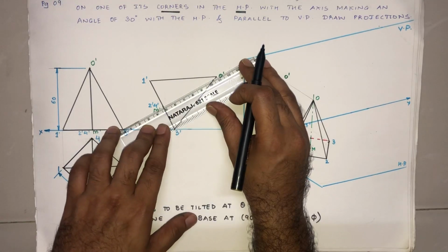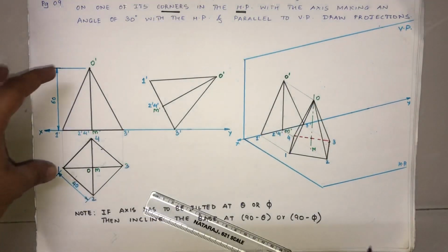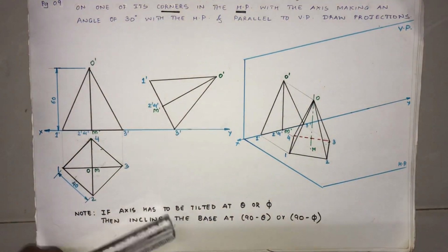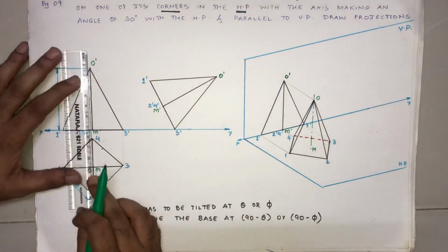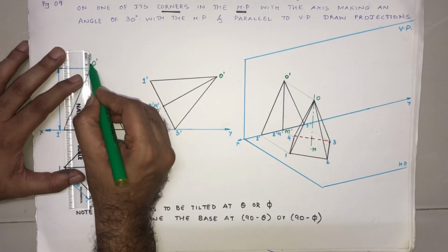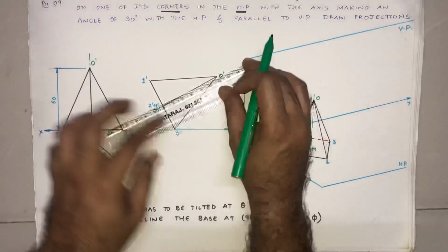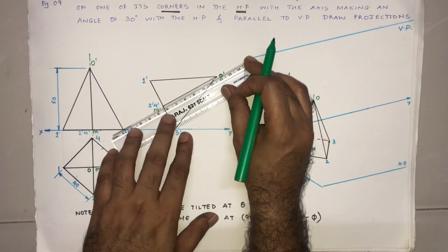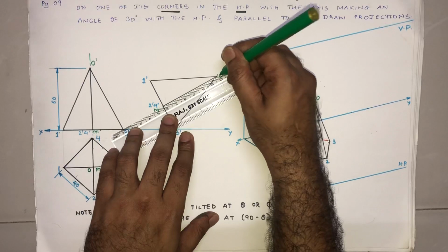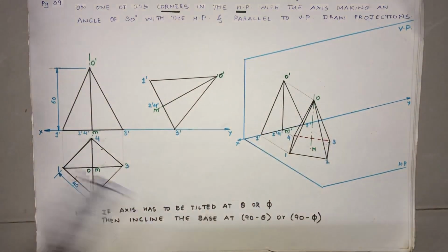And this is that edge in between. So I have actually copied the entire thing as it is. Now, a small point, always remember, since the center line is always imaginary, always extend it a bit outside the solid, because we would want to denote that it's an imaginary line.